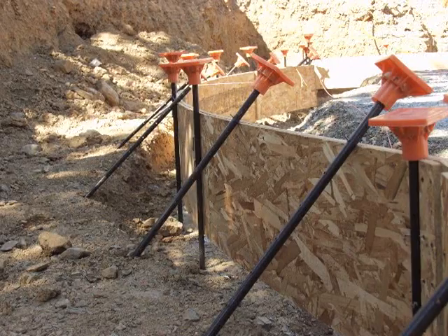You can see here all the angled stakes that we've got in here and the verticals that are holding this OSB form in place. Now it's difficult to get a thick enough piece of OSB to bend, because you have to have it thick enough to hold the weight of the concrete without bowing out in between the stakes. So we use one sheet of 1/4 inch and create our shape, and then we come back and screw another sheet onto that, giving us a 1/2 inch full thickness. But it's too difficult to bend a 1/2 inch piece, so we use the two 1/4 inch in its place.